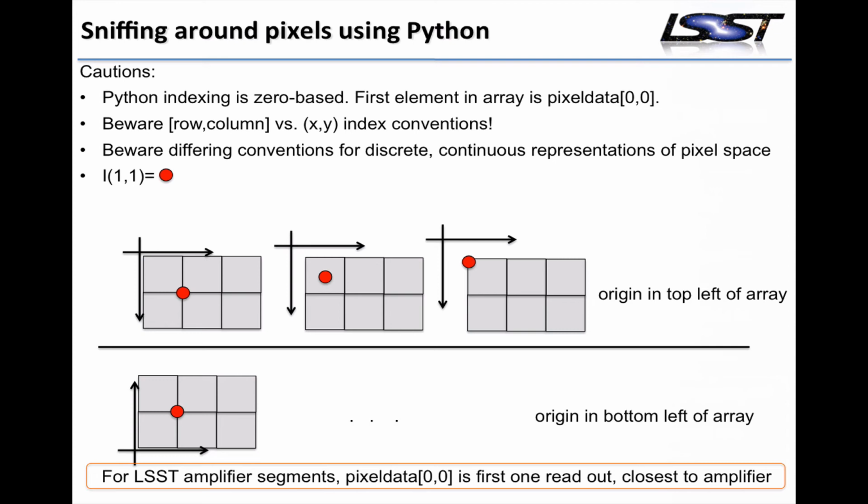And there's a nefarious problem as you take data from one standalone tool and move it into another standalone tool about what implicit assumptions are made about the origin of the continuous pixel coordinate system. And there's this 1 pixel, half pixel ambiguity that rattles around if you're not careful.